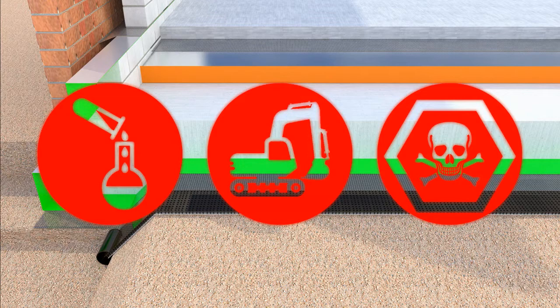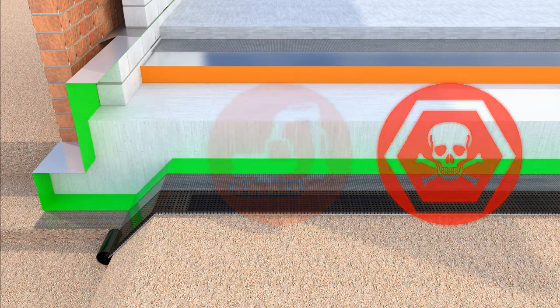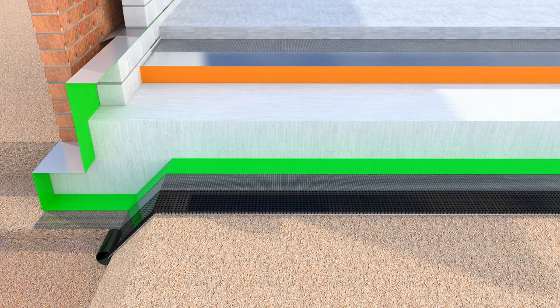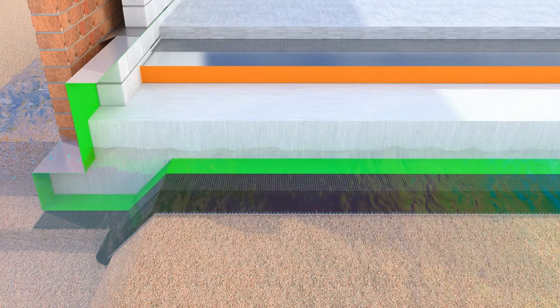For example, by means of a source remediation or by ensuring that the barrier is located in the structure such that contact is impossible. In our example here, if the membrane is located underneath the structural slab, there is a risk the groundwater may bring contaminants from the source into contact with the membrane, which is a particular risk where the presence of water may act as a catalyst and increase the rate of degradation. To resolve this issue, the membrane spec could be increased to improve the chemical resistance, but this may increase the cost and make installation more problematic.